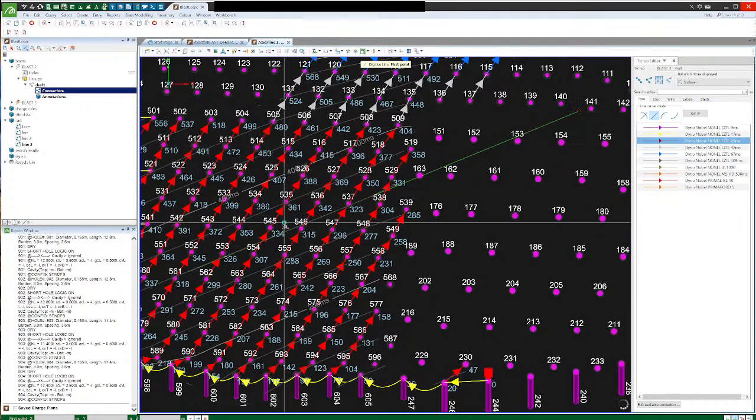So this number, whatever contour timing that is, which is about 325, yeah. We want that time to be there. So this hole needs to be firing at 325. So what's that going to be? There's 1, 2, 3, 4, 5, 6, 7, 8 spaces. 8 spaces.